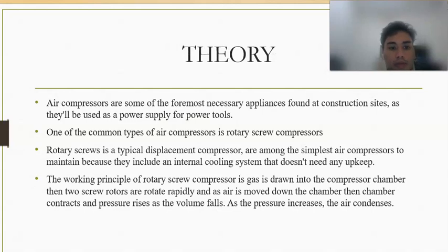For the theory part, air compressors are some of the foremost necessary appliances found at construction sites as they will be used as a power supply for power tools. One of the common types of air compressor is rotary screw compressor, which is used in this utilization by diesel pilot plant. Rotary screw is a typical displacement compressor and is among the simplest air compressors in the market. It is because it includes the internal cooling system that does not need any upkeep.